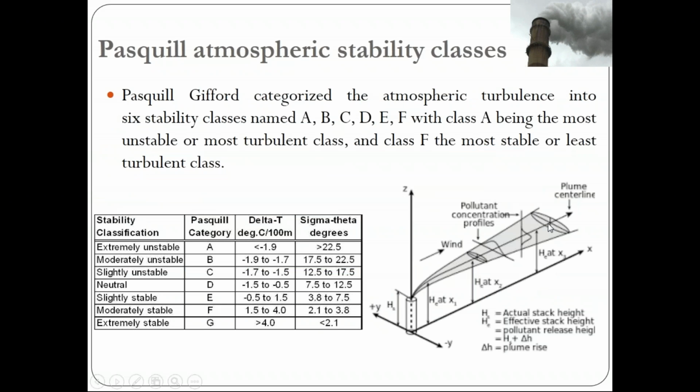So you have to calculate the GLC on the x-axis, meaning at which distance your GLC will be there. This is the distance on the x-axis only, and the y-axis is your whole premises, and this z is the height of your chimney.